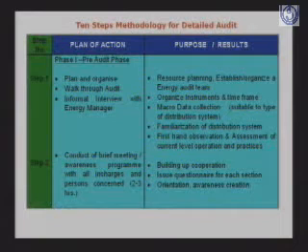In the pre-audit phase, there are 10 steps in the total detailed audit. In the first step, what we are trying to do is planning. We are in the planning stage. We are organizing ourselves. We are having an informal interview with building managers or the system managers. Second, we are having a brief meeting with all the in-charge heads, so as to build up cooperation.